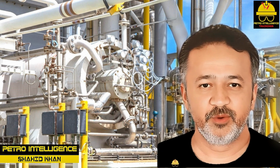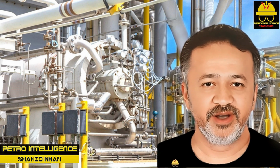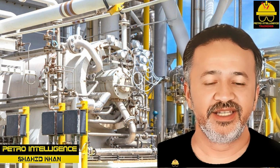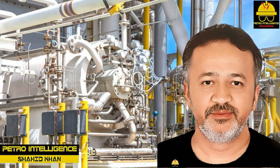Another feature associated with the rotary screw compressor is its ability to be used as a vacuum device. This system is designed to handle 500 to 10,000 cfm on the suction side and to pull a vacuum between 5 and 25 inches of mercury.